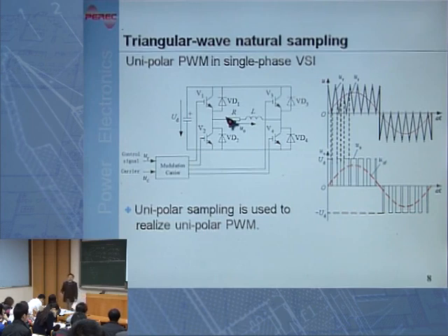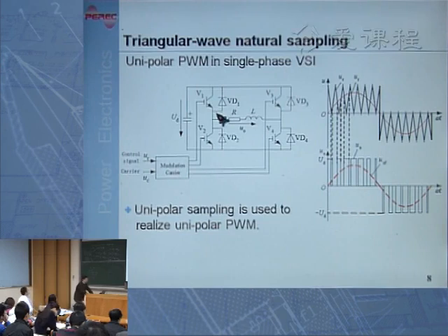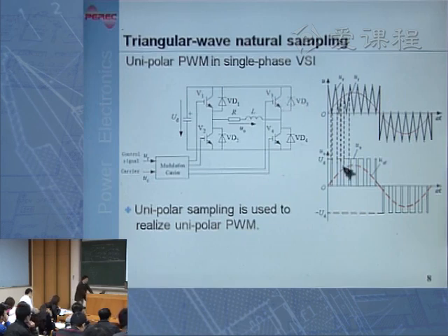Okay? So as long as we send turning on signal to V1, V4. And because in the same half bridge, for voltage source inverter, we always control the devices in the same half bridge in a complementary manner. So when we send turning on signal to V1, we send turning off signal to V2. When we send turning on signal to V4, we always send turning off signal to V3. So that's clear. So that is how we generate this positive UD output voltage.